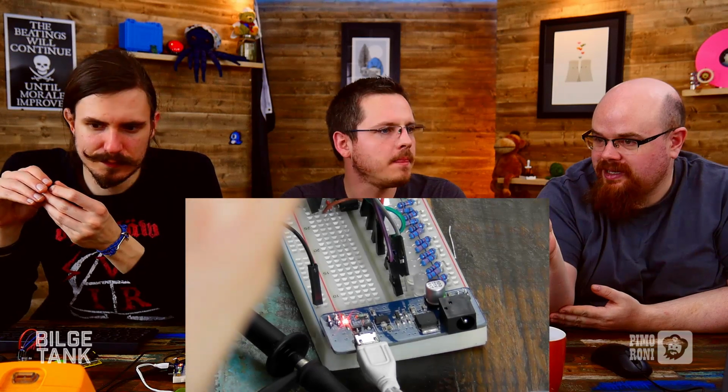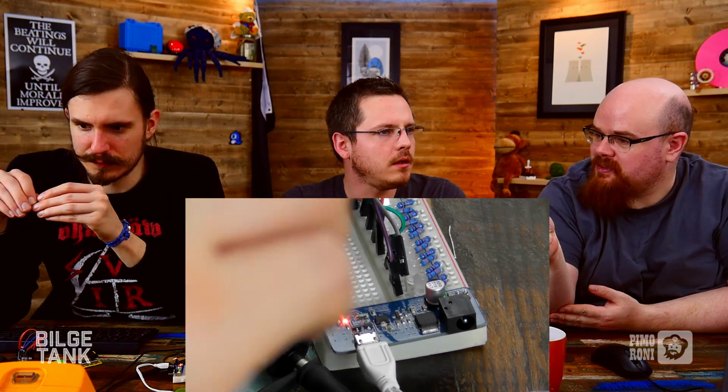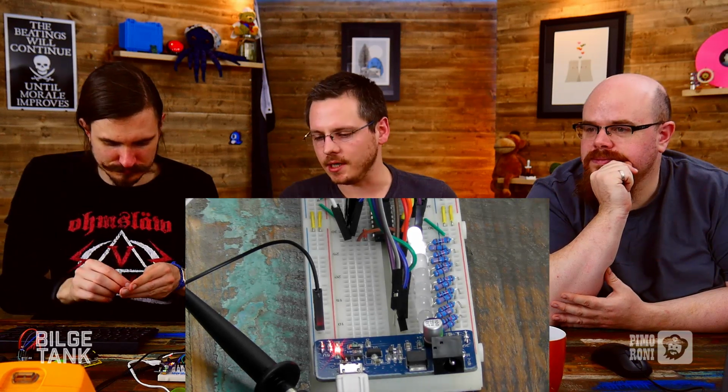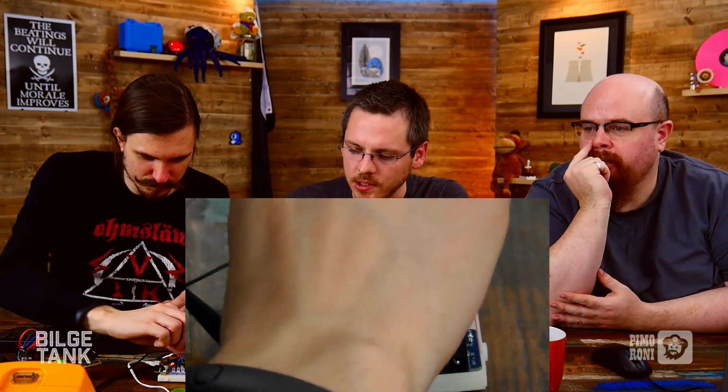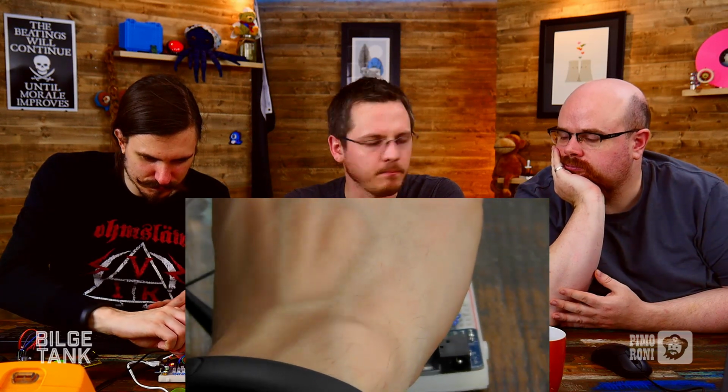So can we start messing with the frequency? See what happens with the sine wave? Yeah, of course we can. So at the moment I've set it up with something slightly interesting with op-amp comparators: quite often the logic voltages we work with tend to be lower than the rail voltages. It depends on the part and there are certain limitations. But that means that what I'm actually doing is running all the logic at 3v3 on here, but supplying the